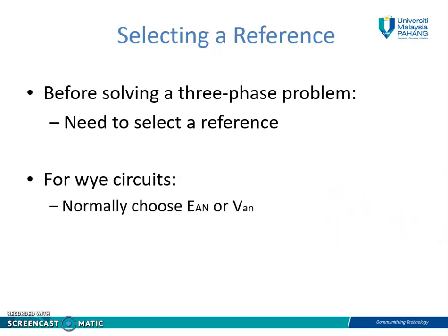Selecting a reference. Before solving a three-phase problem, you need to select a reference. Normally for the Y circuit, we choose EAN or VAN.